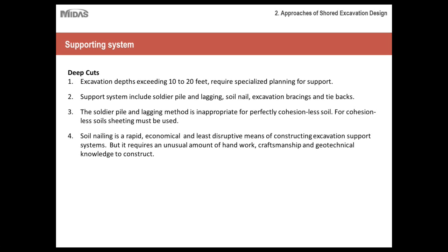Then the next method, and a very popular method, is soil nailing, which is a rapid, economical, and the least disruptive means of constructing excavation support systems. But it requires an unusual amount of handwork, craftsmanship, and geotechnical knowledge to construct this type of supporting system.